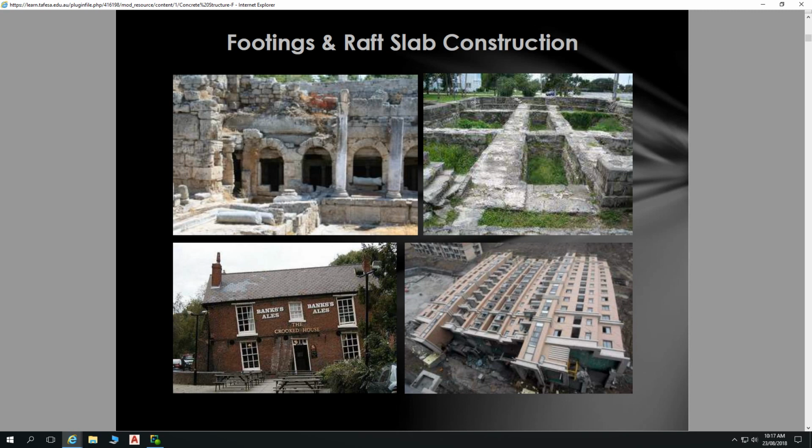That's to ensure that we don't get moisture, because moisture does transfer through concrete, and we don't want moisture coming up through the concrete, which carries salts in it, and those salts being deposited on top of the slab. Has everybody seen salt damp before? Deposited salts come to the surface, then the water evaporates, leaving the salt behind. The salt forms crystals, and it wedges off little particles of stuff. We don't want that happening. We don't want deposited salts coming through on our floors underneath our carpet, etc.